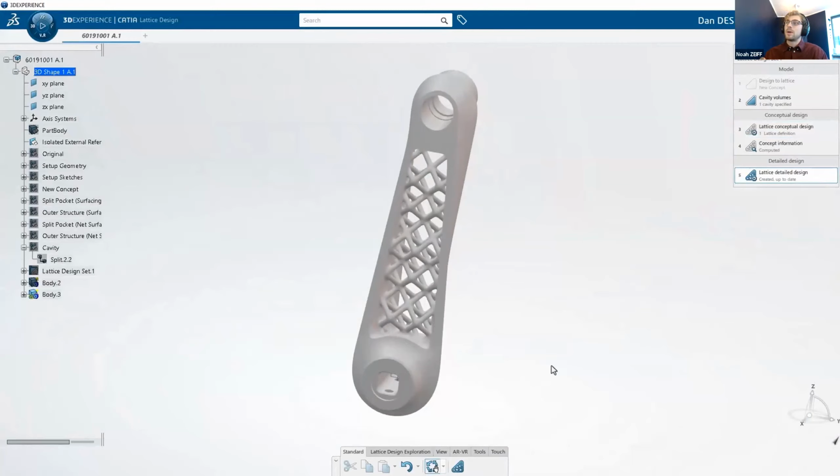And the best part about it is with other lattice tools I've used, once you generate the lattice, you're kind of locked in. It becomes a mesh and it's not very editable. Here, at any point in our workflow, we can go back into the Lattice Design app, edit the size, the length, the radius of all of these lattice cells. And that's true if we want to edit the X-Shape geometry as well. So Gian, if you made another edit to this outer shape, we can update the lattice geometry to that new shape, similar to what we did with X-Generative Design.